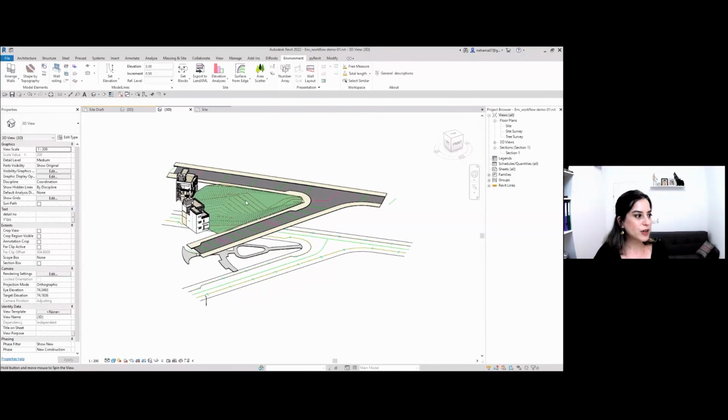And basically environment is going to automate the process of modify sub elements. So it's going to add the elevation points to this floor, as you can see right now, on top of the topography. Now, just a side note, we usually do preserve these topographies in the file, not for scheduling purposes, but to be able to edit or re-edit our slabs if you want later on. So we actually have a dedicated view filter for that. So now let me just hide the topography and hide this auxiliary line. And there you go. We have the complete